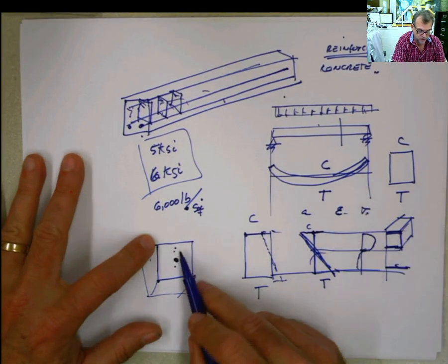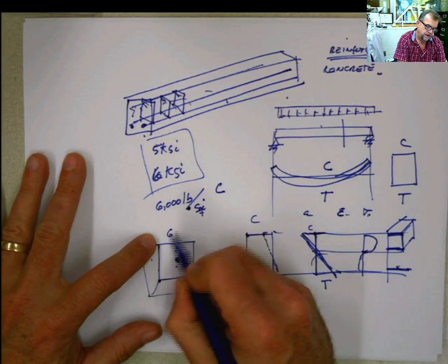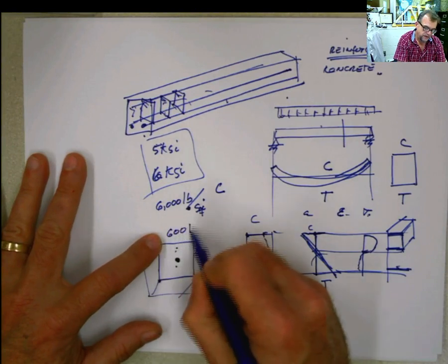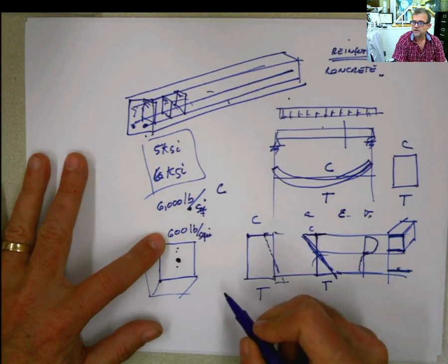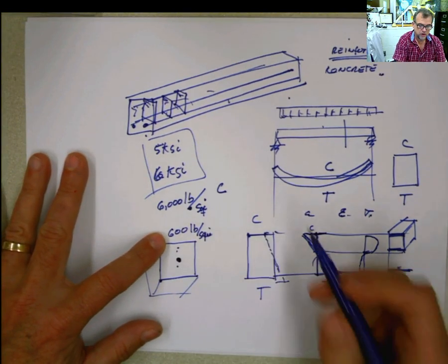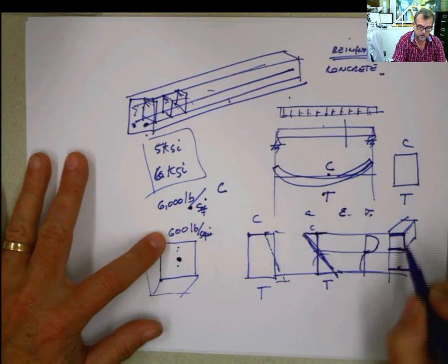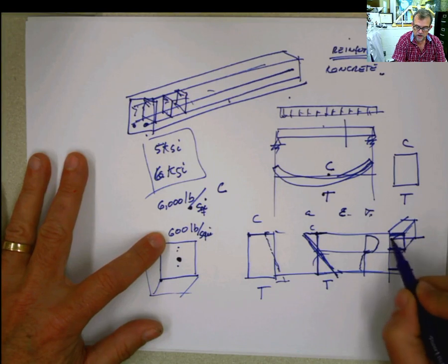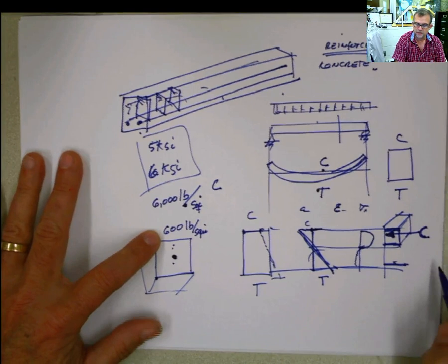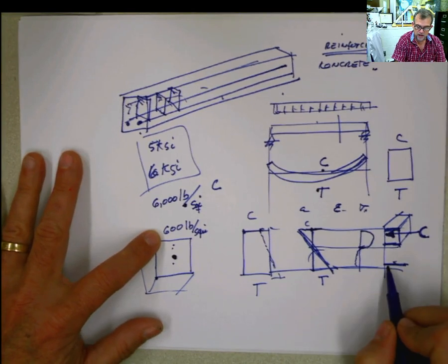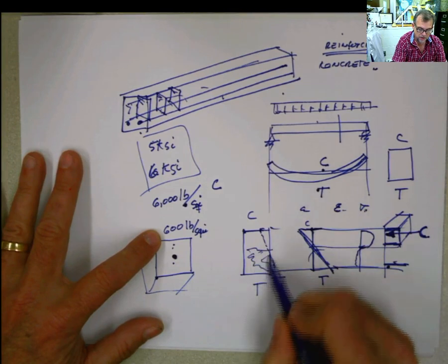However, in tension, that material, let's talk about maybe 10%, 600 pounds per square inch, which is still something, but not that much. Now in the top part, as you remember, it was compression. In the bottom part, it was tension. So this part, the concrete is able to resist that compression perfectly. But at the bottom part, the concrete is going to start cracking everywhere.